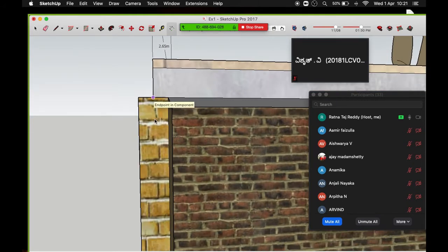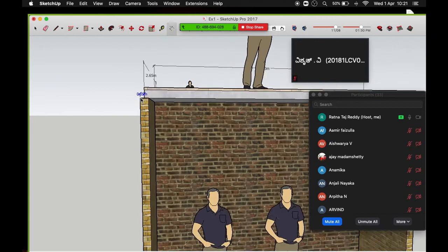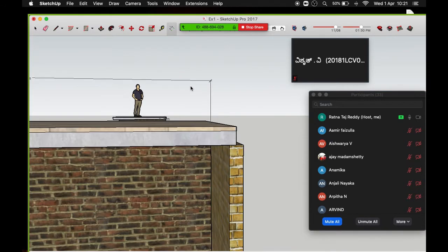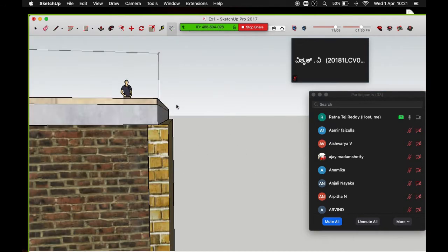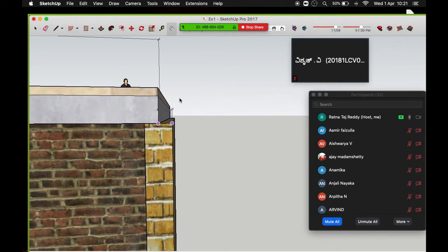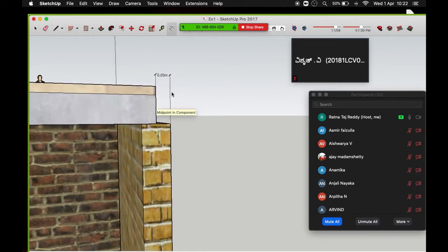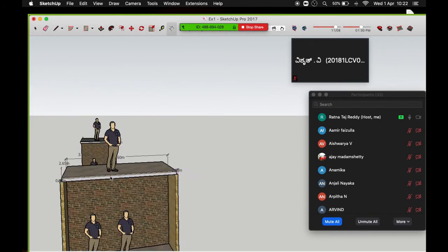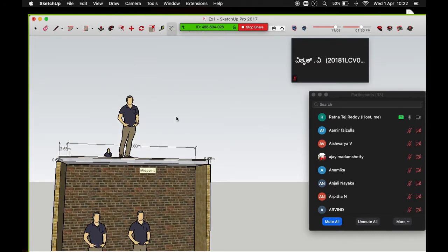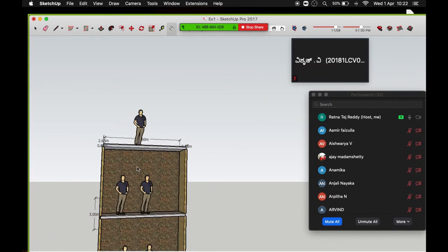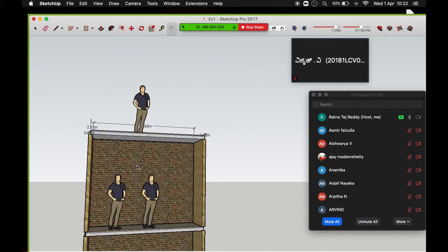That is the cross wall which is happening over here, which is 100 mm thick, and the center of 100 mm is nothing but 50 mm. Again, another cross wall which is happening on the other end, which is 100 mm thick, and the center would be away at 50 mm. So that is what that calculation meant, 3.6 meter plus 100 by 2, which gives 3.7 meter.